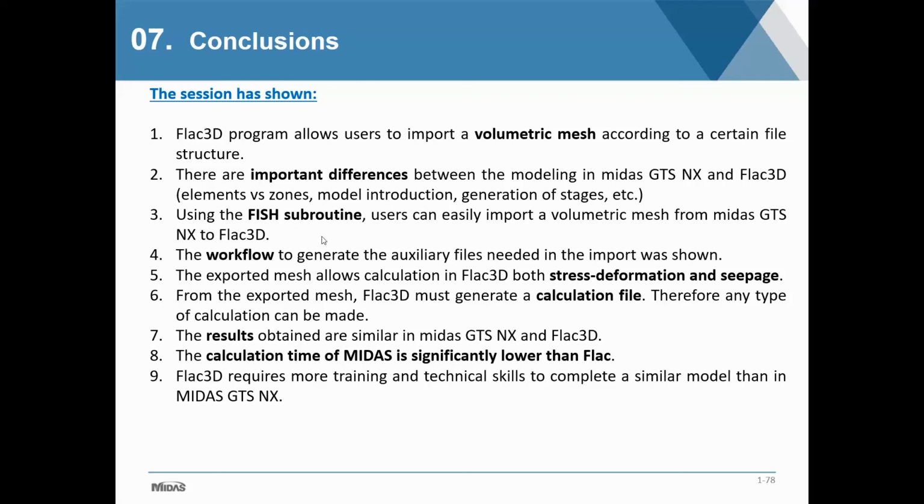Using the Fish subroutine, we can easily import meshes now from GTS NX. We saw the proper format and the proper workflow to make all the files that we need, basically the text files, in order for the Fish routine to be able to import. And then we showed that once this mesh was imported into Flac, we ran it for the stress, deformation, and seepage for 2 examples.